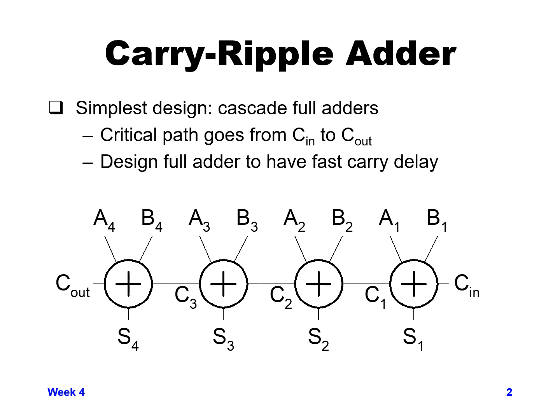If you have a 4-bit adder here, the carry has to propagate through each bit successively, and you have to wait for the previous bit. This is a simple design, but it's a slow design. We'll look at different techniques to make a faster design than this, because for very large data paths, you can't wait for this amount of delay, or you'll be operating very slowly.